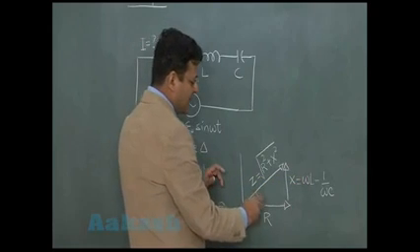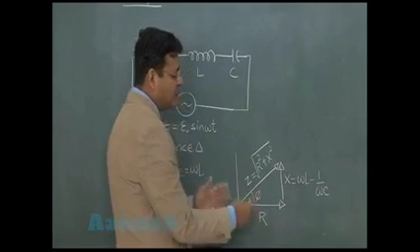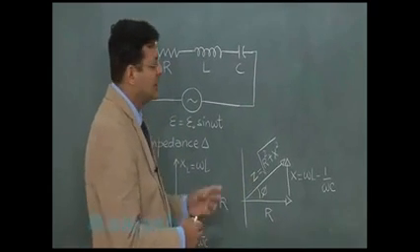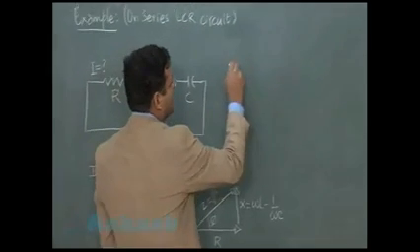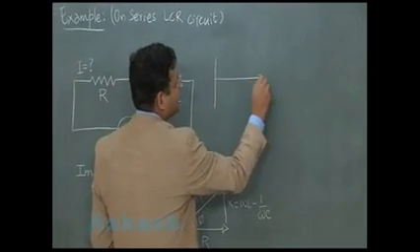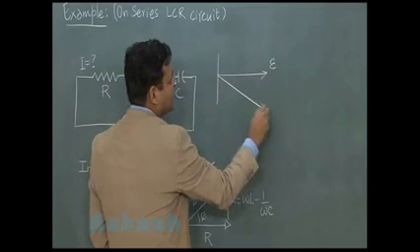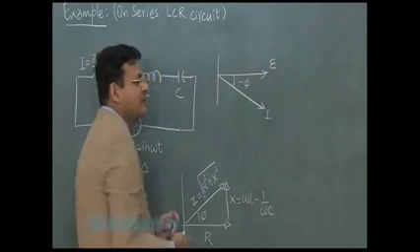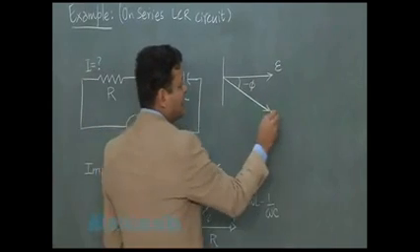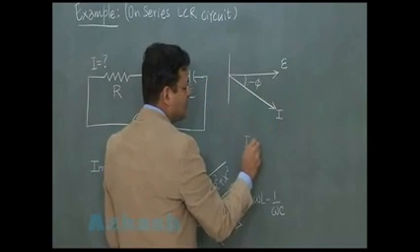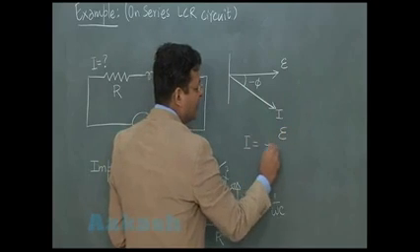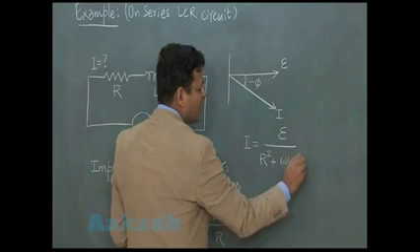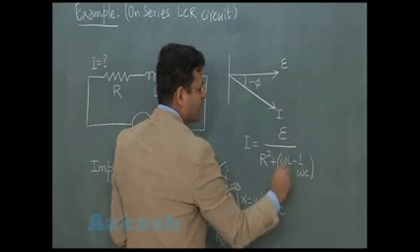For the time being, you can say the angle is phi, and this phi will be utilized for calculating the current. अगर ये phi की value यहाँ positive है, then in case you are showing in phasor diagram, then EMF as a reference will be drawn this way, and the current here will be drawn this side, making some angle minus phi, or you can say the current will be overall lagging the EMF, and the expression of current you will be getting as EMF upon the square root of R square plus omega L minus 1 by omega C whole square.